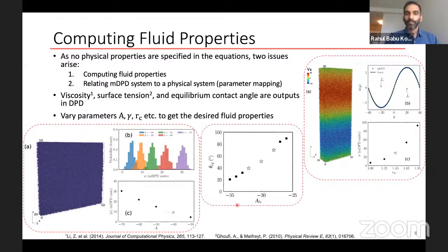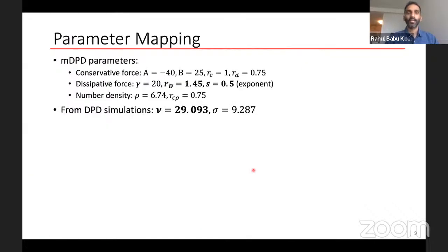Next up, we looked at the equilibrium contact angles. We wanted to stay as close as possible to the experimental evidence, which says that these drops spread rapidly and wet the TBC to a very high degree. So we only use three shallow contact angles, not so shallow, like 70, 55, and 39 degrees. And these are the parameters that we have obtained.